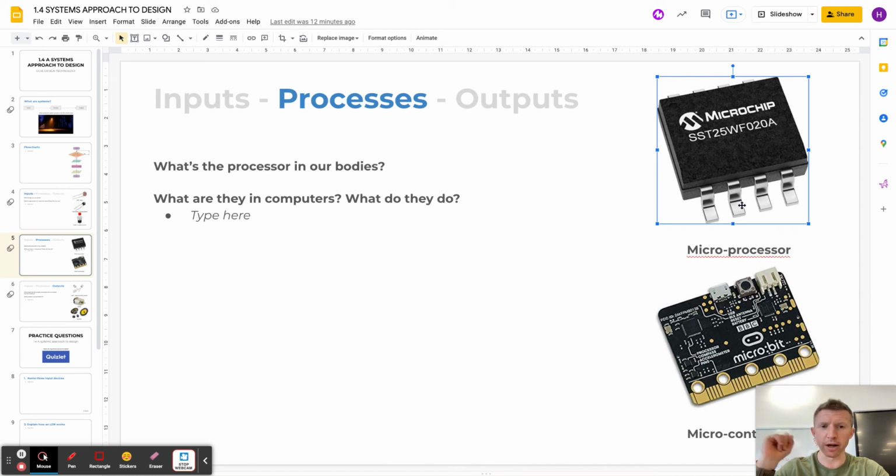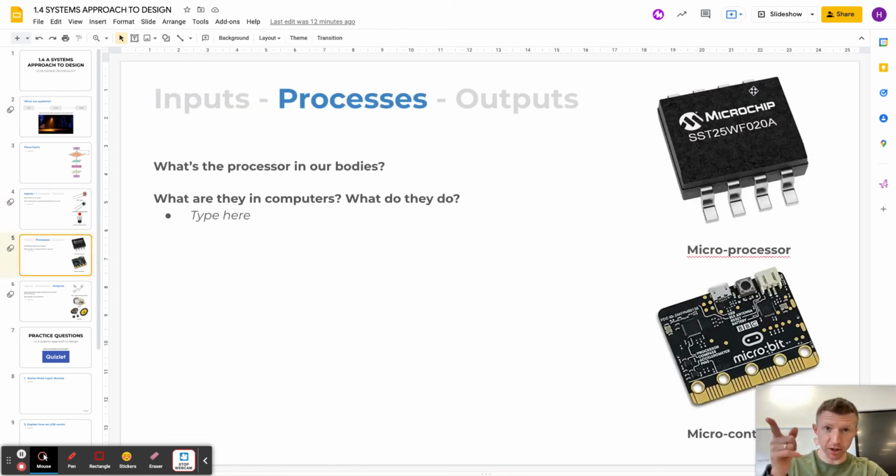You can say, right, I'm going to link pin 2 up to an LDR, and then pin 5 or pin 6 around here is going to go out to the light bulb. Then you program the microchip and you say, when the LDR reaches this certain level and you start getting a bit of voltage here, we want you to turn on a switch inside to turn on the light. And so they're basically decision makers. That's really what they are.